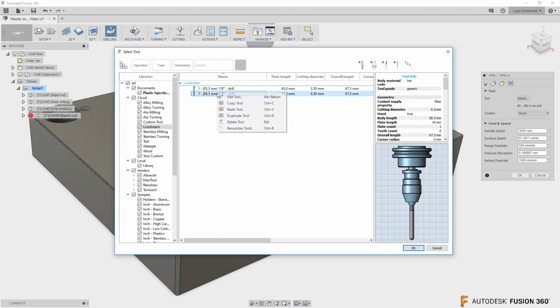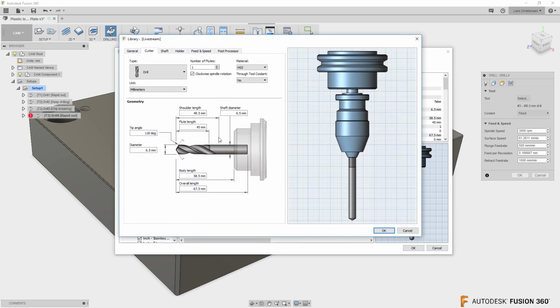I'll go in here, I right click and I duplicate one of these tools. I right click and I edit it. And now I know these are 14mm holes for those counterbores. For the screws, 14 and 14. And you can see here that the tool is probably longer too, but this looks a little weird. Actually, I never use drill chucks in a CNC mill.